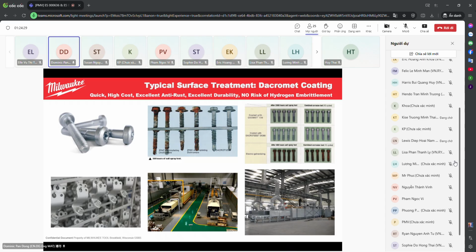First, cost. Dichromatic plating cost is quite high, much higher than the traditional electrolytic plating. And of course, the surface coating layer thickness cannot be achieved as uniform as electrolytic plating. So if for some parts we have very tough dimension requirements, that would be a concern.